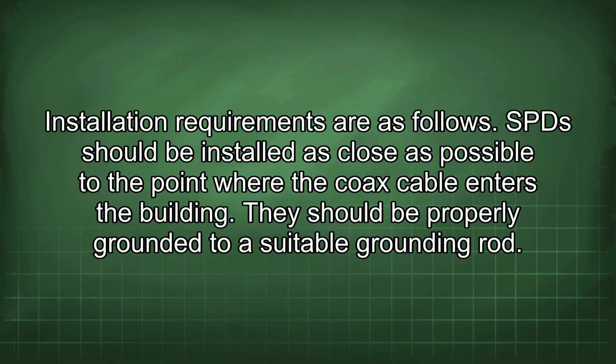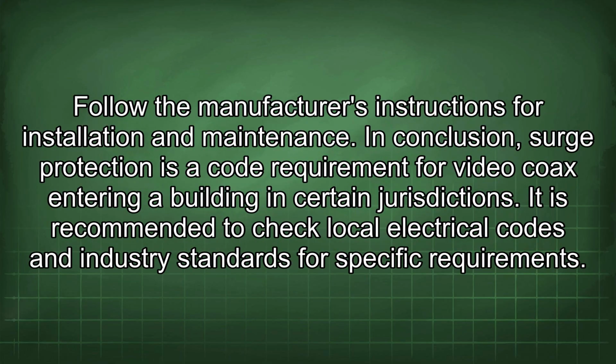Installation requirements are as follows. SPDs should be installed as close as possible to the point where the coax cable enters the building. They should be properly grounded to a suitable grounding rod. Follow the manufacturer's instructions for installation and maintenance. In conclusion, surge protection is a code requirement for video coax entering a building in certain jurisdictions. It is recommended to check local electrical codes and industry standards for specific requirements.